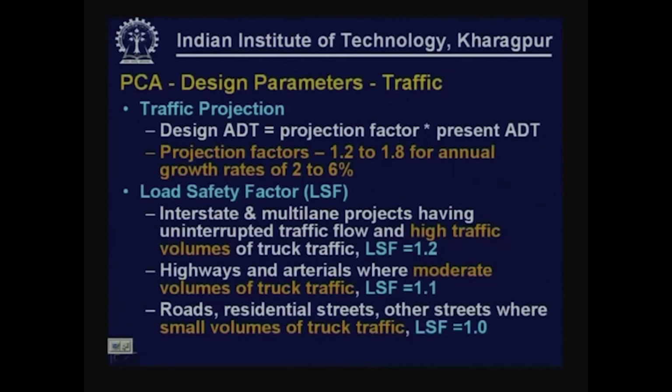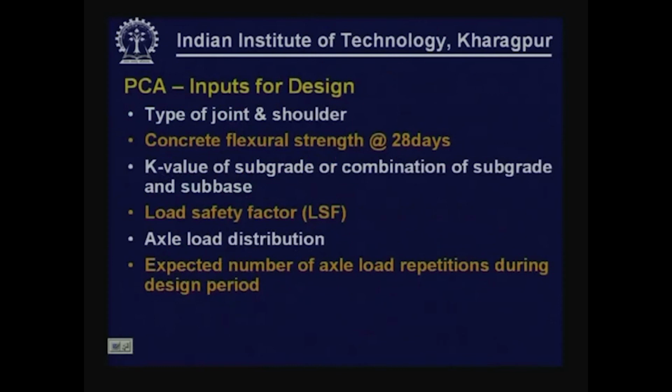PCA also recommends usage of load safety factors, LSF, as we have done in the case of IRC 58 also. For different types of facilities, different load safety factors are given. As you can see here, for high traffic volume roads, load safety factor of 1.2. For moderate volumes of truck traffic, load safety factor of 1.1. For residential streets, other streets where small volumes of truck traffic is there, load safety factor of 1 can be used. These are similar to the values that were adopted in the case of IRC 58.